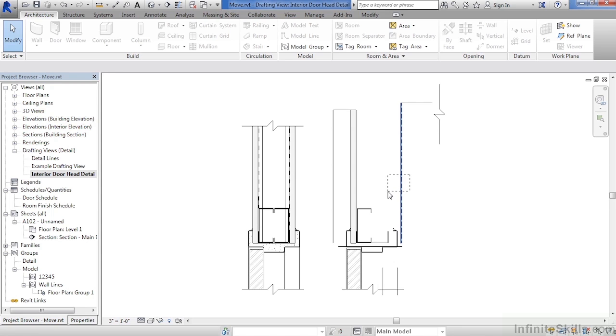This is called a crossing window. When you see a crossing window, it means that anything that's touching this box will get selected. If you had selected on the other side of the line and then moved over to the lines, your box would have looked like this. This is a regular window, and all of your lines would need to have been inside of this box in order to pick the lines.